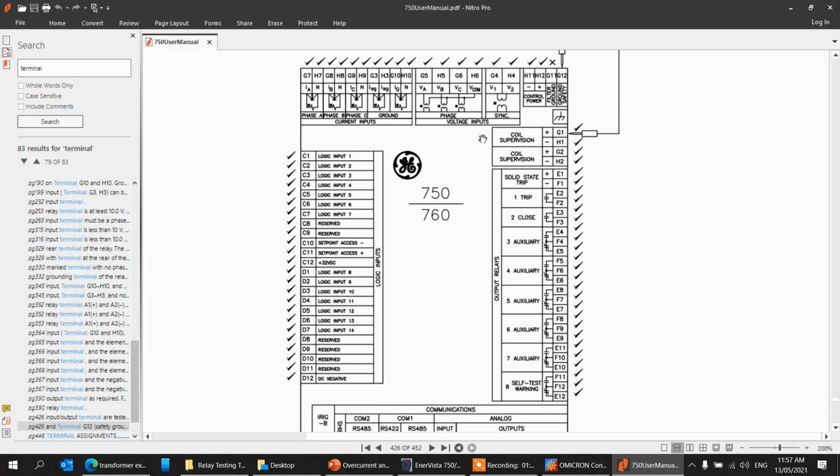Of course, you have the ground fault and REF. You make sure that one is connected properly as well, because some of the relays have a separate signal and some of them are zero sequence. So you have to look at those things, which one is wired or not wired. You have all those documents: the setting, the hardwire, the schematic drawing.